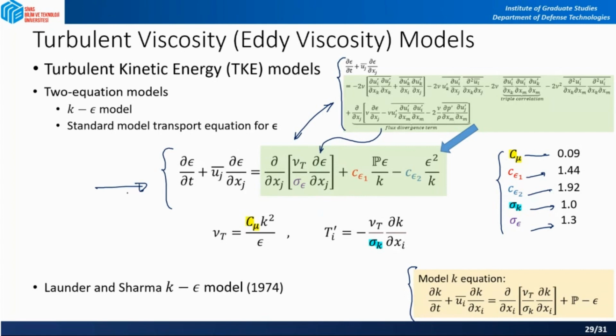And those constants that you see shown in the table are all embedded in all CFD codes that you use today. Those constants are derived based on some experimental data which were specific to one experimental case. So there is no guarantee that you can use those constants in some other turbulent flow cases.